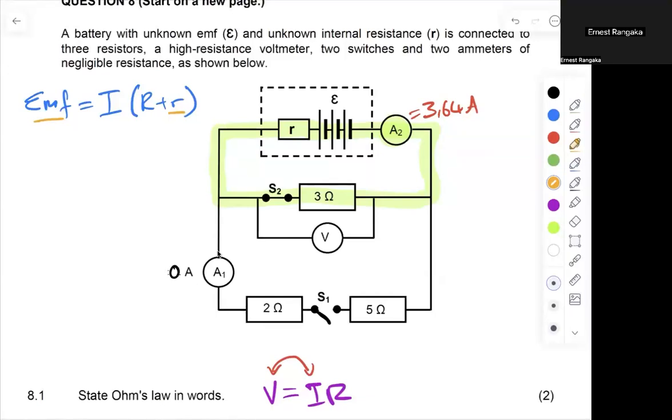So now how do I get my second equation, right? I need two equations to be able to solve this, which on my side is not going to be bad because I've been given two scenarios. I've got the scenario where my switches are all closed. That is one scenario. I will use that equation. Then I've got the scenario where my one switch is opened and I've got new information. So now I can use that information for both of those. For that one EMF, write it two ways and then solve it simultaneously.